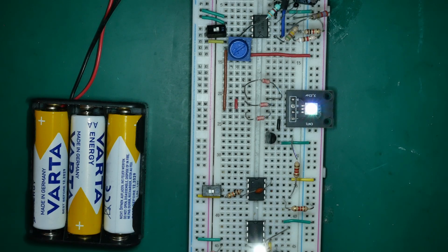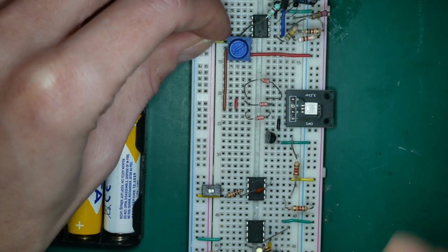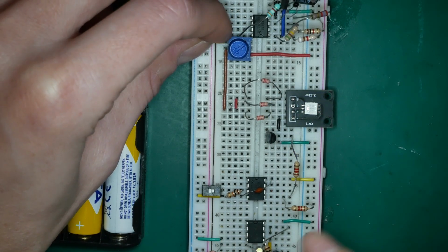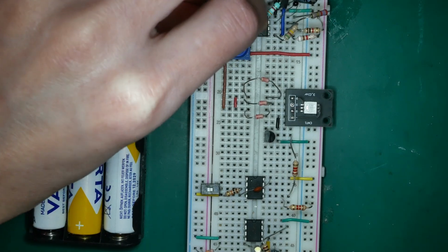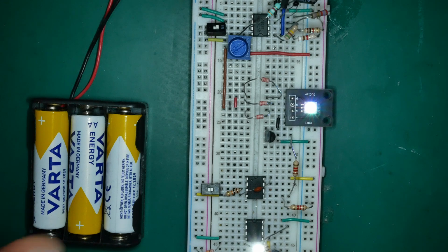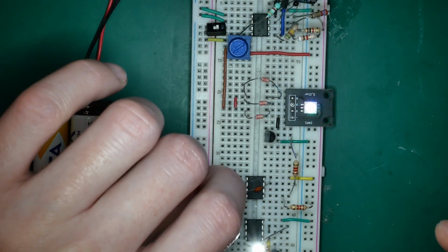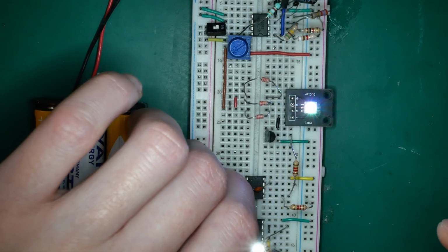Immediate switching could introduce a lot of problems. I would need to deal with switch bouncing, rapid user input, and carefully synchronize all timers and states. With this approach, none of this really matters. The system just waits for a neutral transition point and everything stays stable. In this case, fast reaction to the switch isn't necessary. So this solution is much cleaner and more reliable.